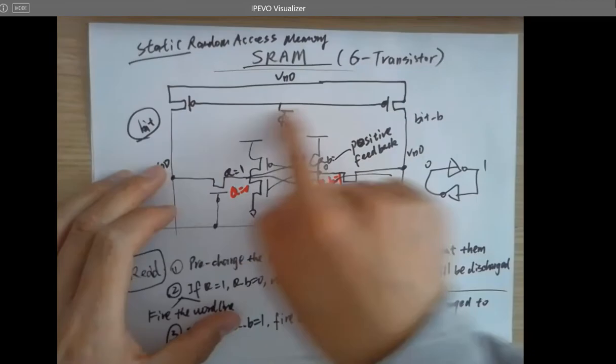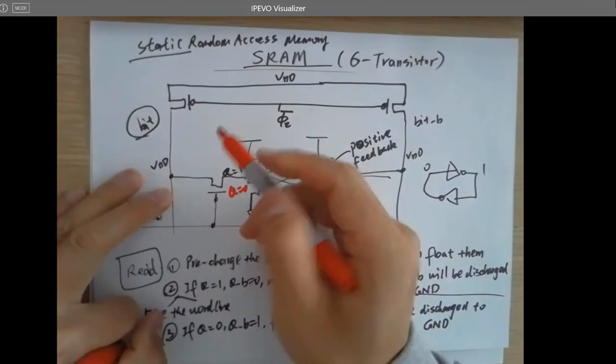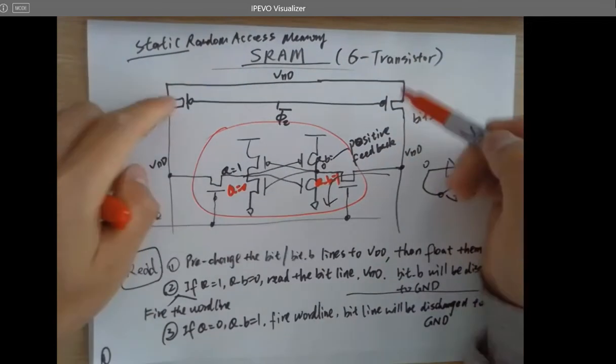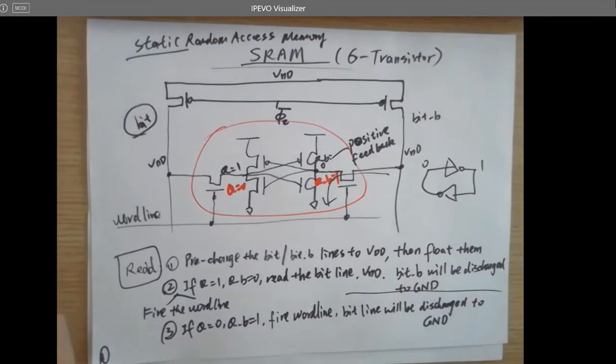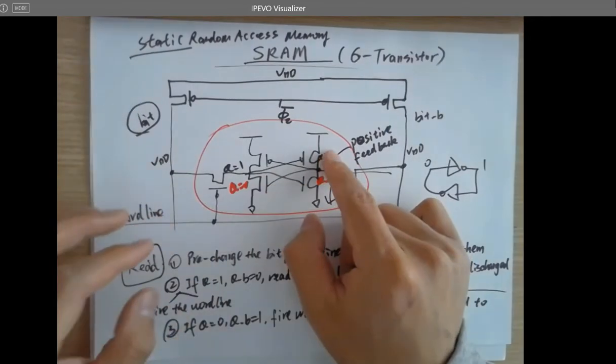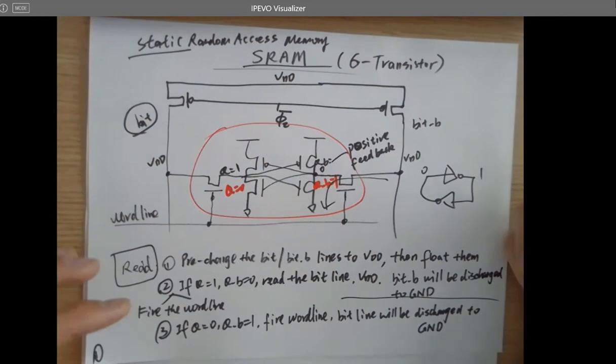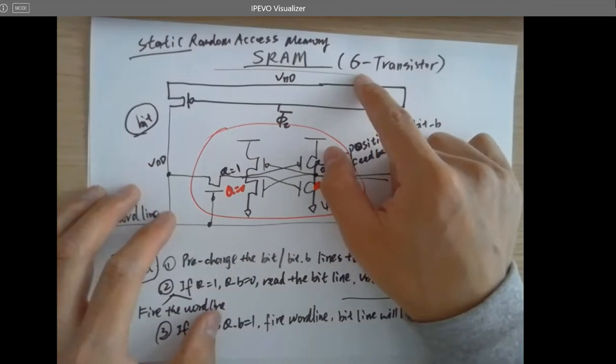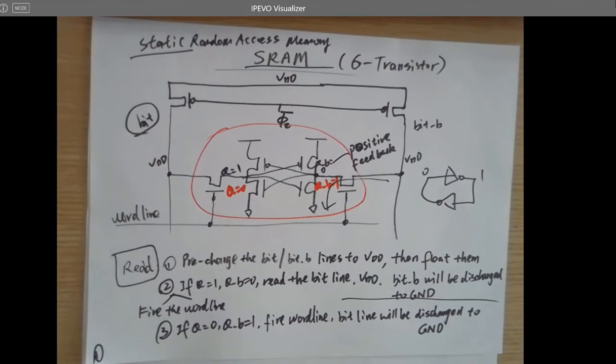Oh, this is a memory cell. That's a 6-transistor memory cell. These are some peripheral circuits trying to pull it up, pull it down. There are many other transistors as well. It's just not in the cell. So that's a memory cell. You can have control bits, you can have decoders, and just everywhere. It's definitely not only 6 transistors. It can be millions. Right?